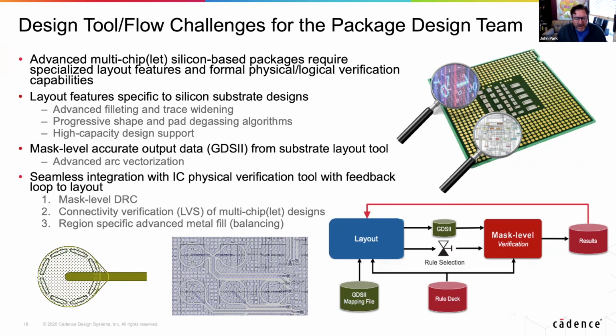But more significantly, you need to be able to output to an IC or mask level physical verification tool for DRC, LVS, and in some cases, smart metal fill. So this is a big change. If you're coming from the package design community used to outputting Gerber, that's going to change. You're going to need a tool that supports this.